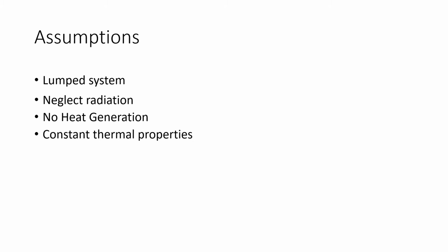So the question said to assume a lumped system. Usually we would do a quick check to see if this is allowed, but I'm going to skip that for now. The question also said we can neglect radiation. I'm going to assume there's no heat generation, constant thermal properties of the material and the surroundings. I'm going to assume this is a one-dimensional equation such that heat transfer is only traveling in the radial direction. It's not traveling in any of the theta or psi directions.